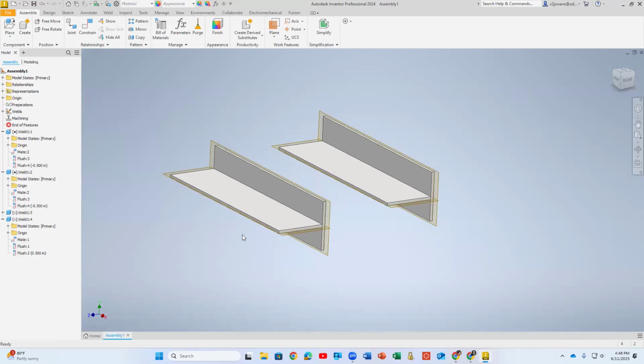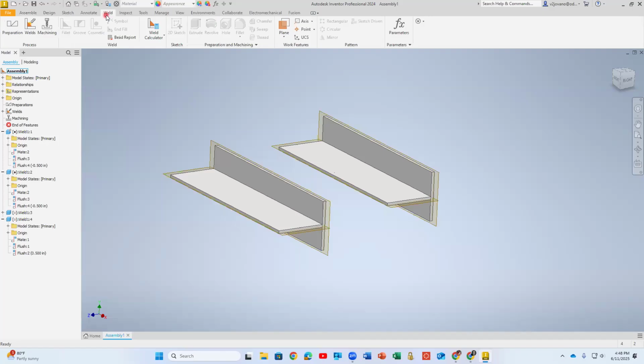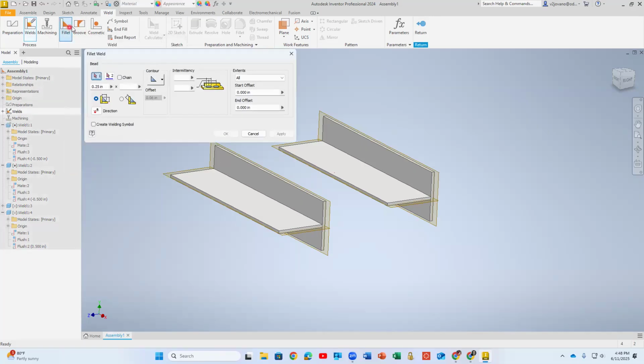So let me see. We will now learn how to create a weldment. That's on page 15.6. So they said go to the weld. You see here, there's a separate part for the weld. We will go there, select welds here, left click there, then we do fillet. And we will say here, flat weldment. So let's see, fillet weld, contour. This is the flat weldment icon.